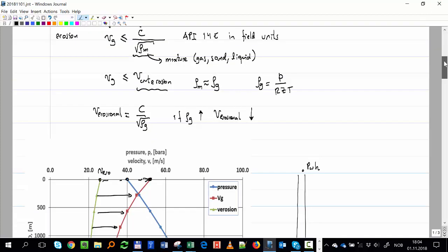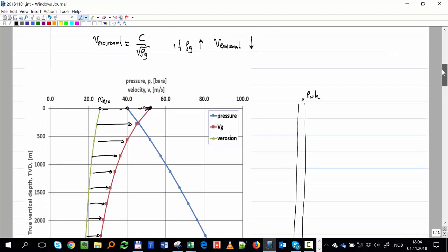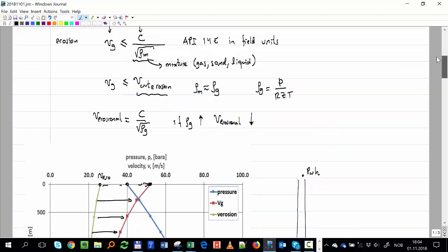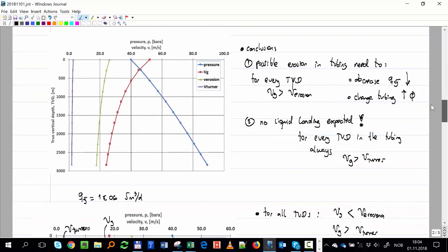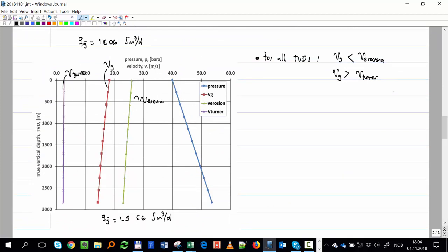So, what are the assumptions that you didn't make here, but are currently being made in those software? Are there any? No, really no assumption. If you have good data to populate your equation, it should give you results very close to the measurement in the field. Some problems you might have are that the pressure has some error, the instrument is not calibrated, or the tubing somehow has a reduced diameter.